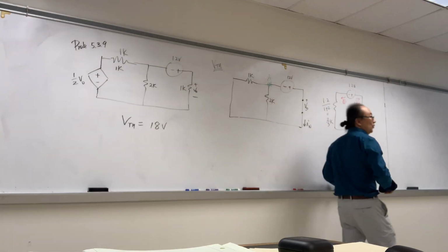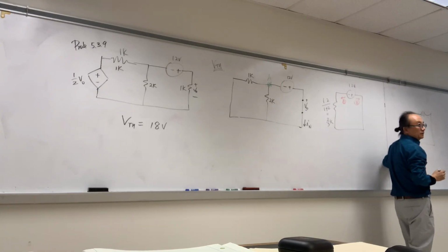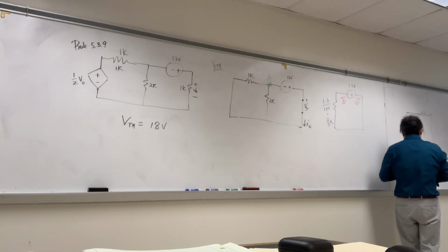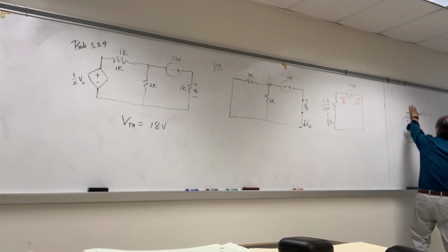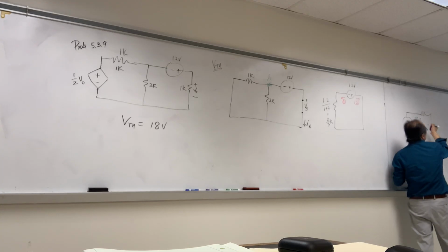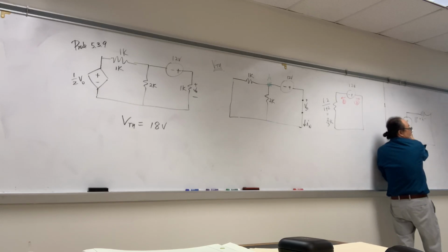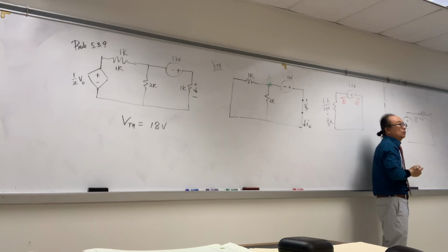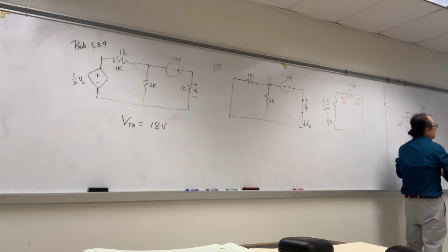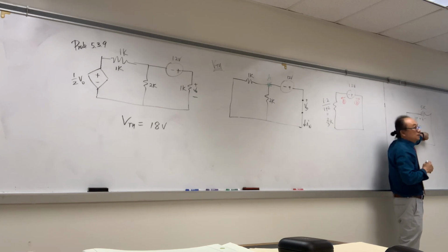1 or 2. You remember the only simple circuit that I drew all the time? If you have this circuit from the first or second day of the lecture, what's the direction of the current we draw all the time? It was 1. So this is higher potential to lower potential. When we assign the polarity for this guy, we're going to call it V1, higher potential to lower, exactly opposite to this. That's why I keep telling you, you need to understand this single loop. Otherwise, it's going to be really confusing. You have to think about KVL. KVL: negative 12, positive 12 equals 0.